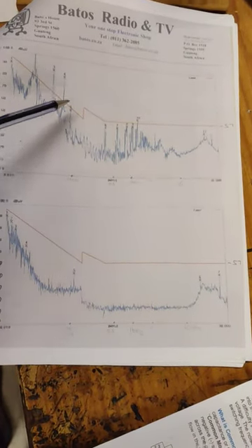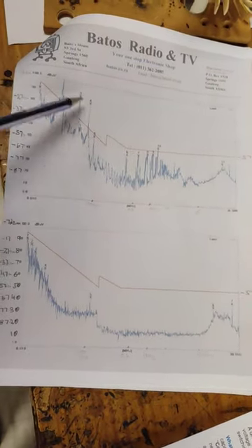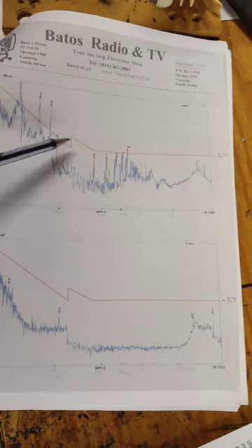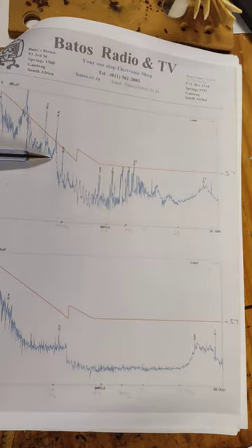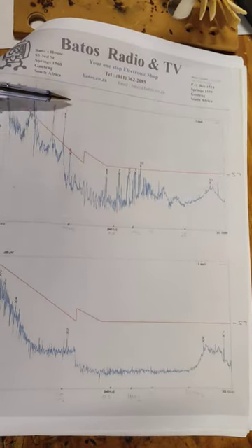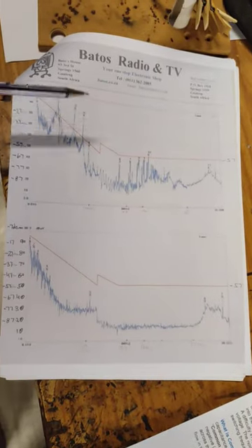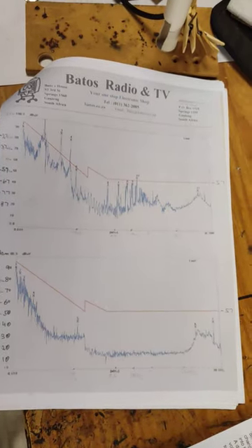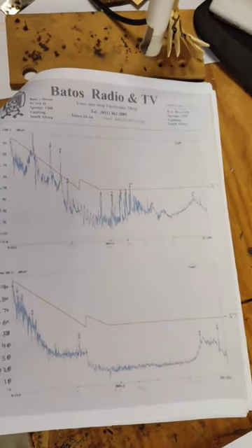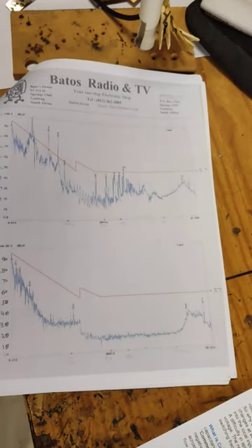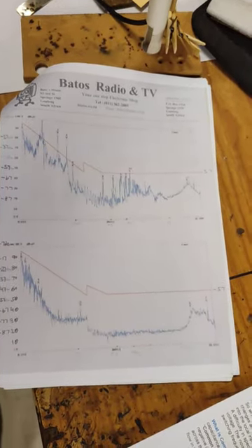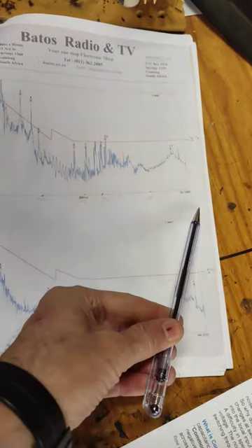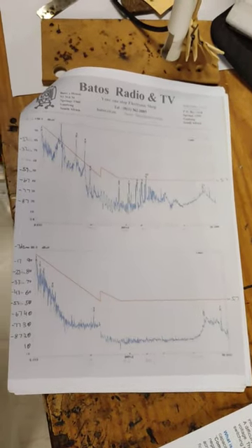There's a load line, and if any signal goes over the load line, even if it's just one spike, it can create havoc. Usually the most common mode noise is generated anywhere between 0 and 30 megahertz, and that's what I have here, a 0 to 30 megahertz measurement captured from the instrument.